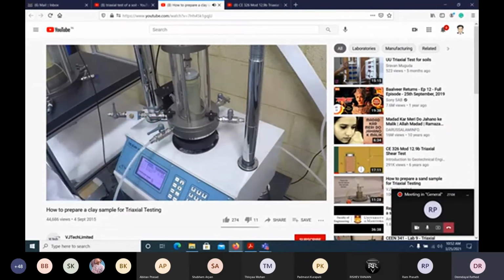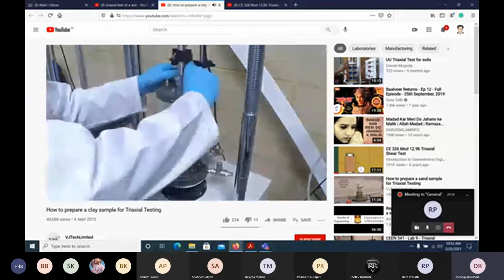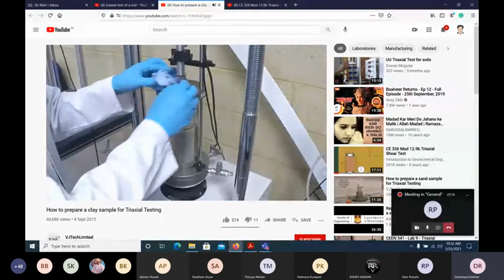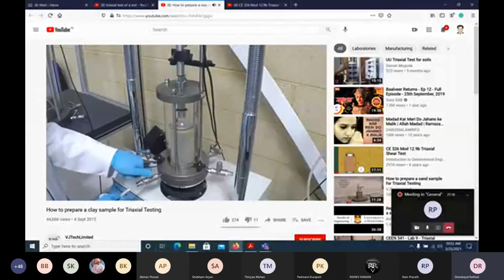It's filling the water, okay? So that's the membrane we generally use. Once it is nearly full, be ready to close the valve as water begins to flow out. So that is a sample preparation technique, okay? Now your cell is ready.